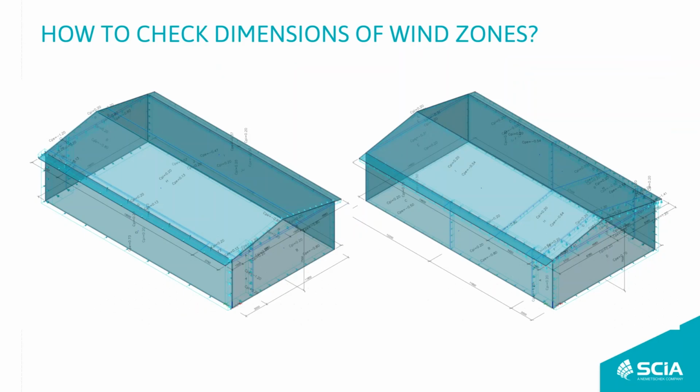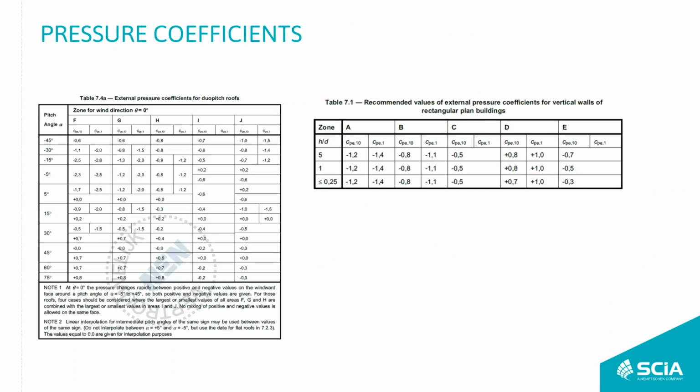While we are waiting on the generation, as I have shown you, it's possible to document the zones and the values, and then via the live picture or via screenshots import it to the engineering report to document how you calculate the wind load.